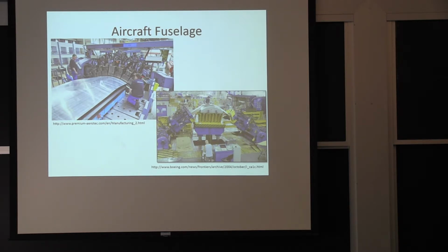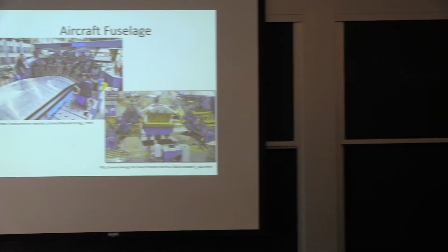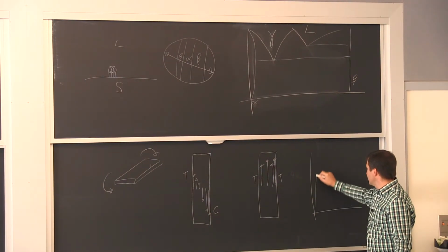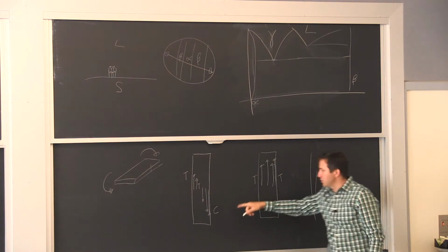If you bend, you agree you're going to have a side in tension and then compression. That's a typical stamping operation. When you stretch form, you're in tension on both sides. So internally, while it's in full load and it's right against that complex shape, the tension through the thickness is approximately the same because you deform it plastically. So you exceeded the yield strain. Initially, it's going to be different, but as you keep deforming, because we have Hooke's law, we're thinking here of Hooke's law because we have tension and compression.